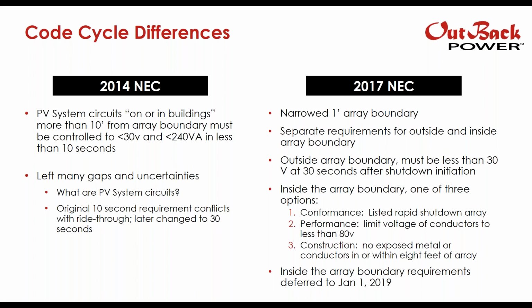So what is a PV system circuit? There was some uncertainty about the definition of that, and I think that became clear in NEC 2017. They cleared that up. Originally there was a 10-second requirement that conflicted with the ride-through requirements, so they later changed that to 30 seconds. So we have NEC 2017.